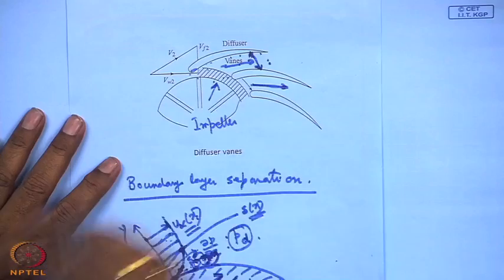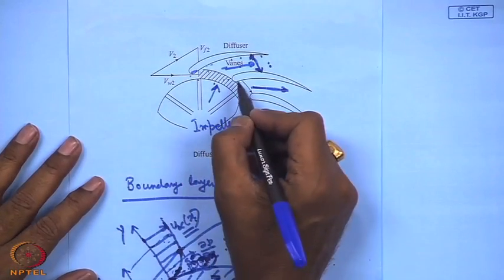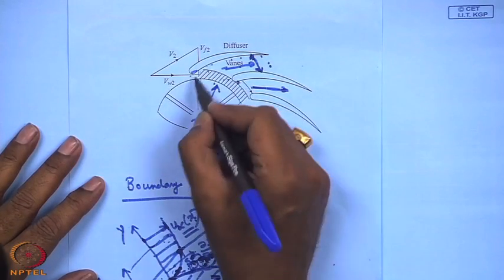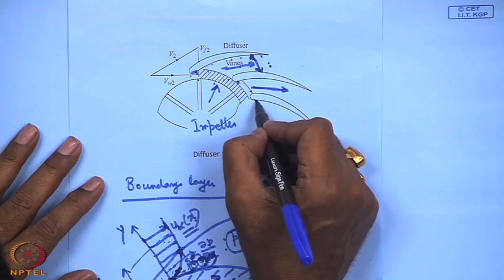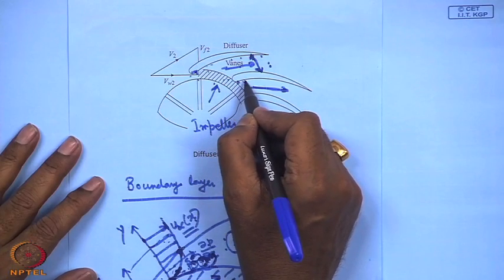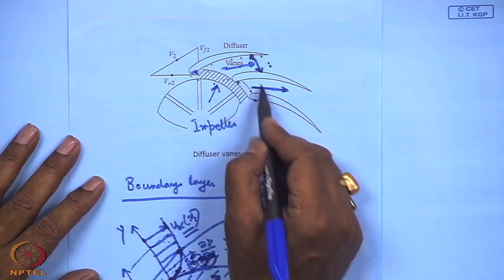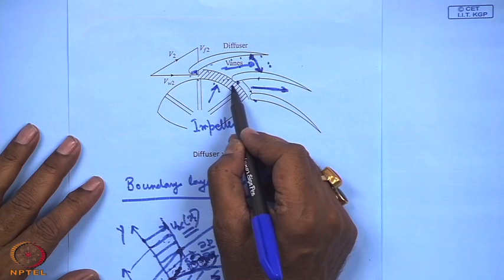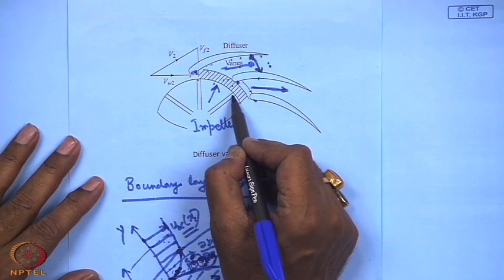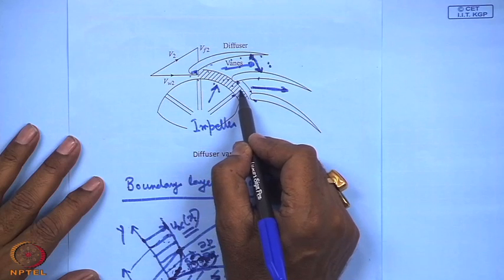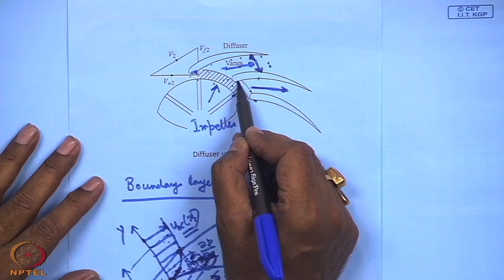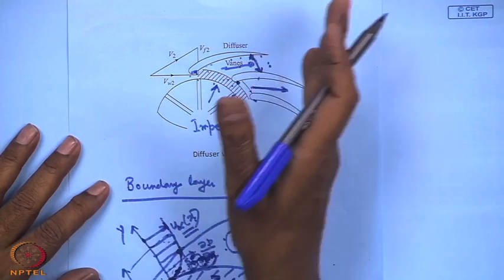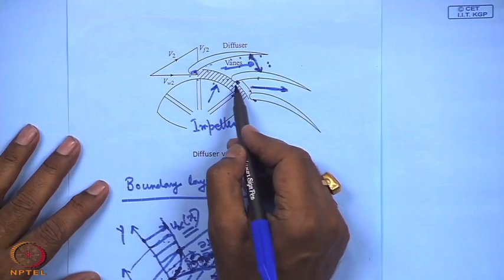Okay? Now, I come to the vaneless space. Now, the divergence angle at the inlet to the diffuser vane should also match with the direction of the velocity, and since the diffuser vanes are static vanes, the direction of the velocity means the absolute velocity, which comes out of the impeller. That direction should match the direction here, otherwise there will be incidence loss.